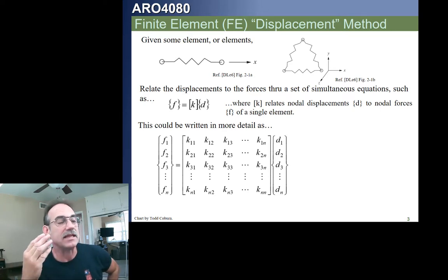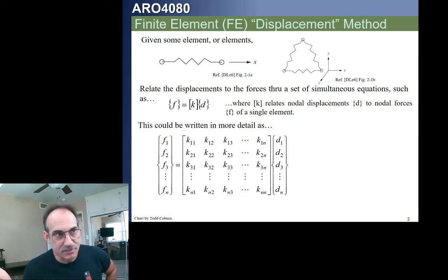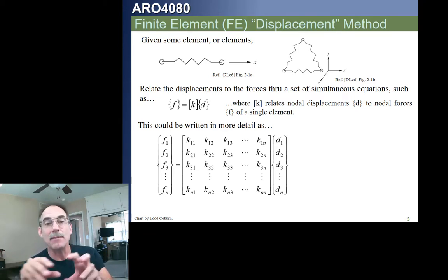And if we look at that same equation where we look at the nodes, like node 1, node 2, node 3, then we could talk about the force at each node, and each element is going to be a function of the displacements at that node times whatever elemental stiffnesses affect the node.